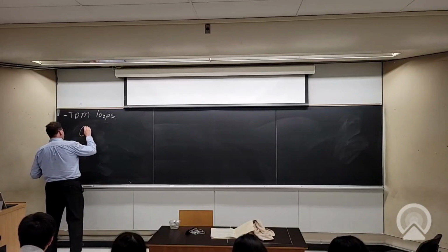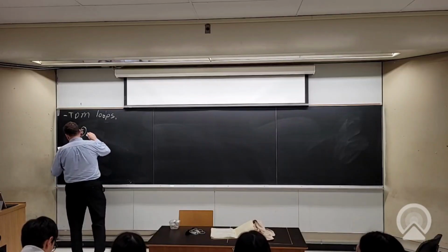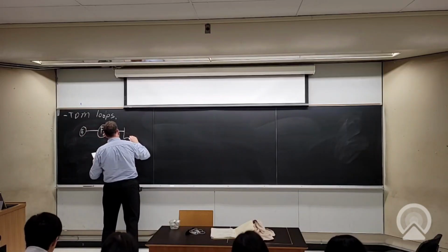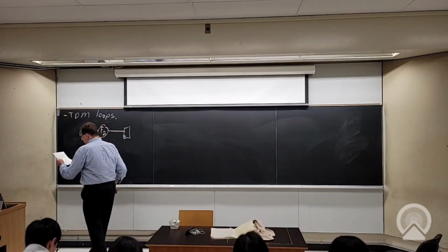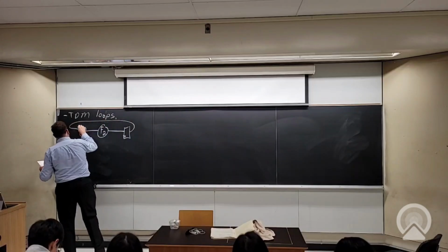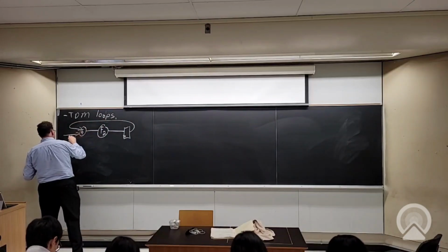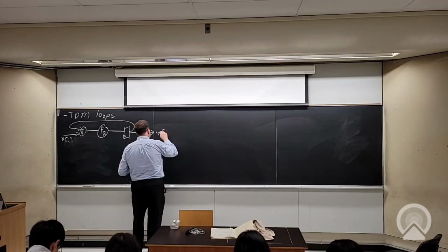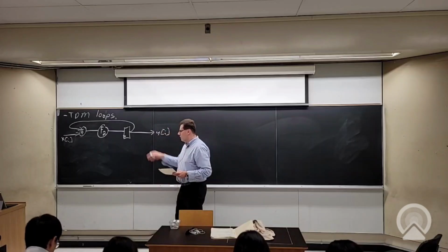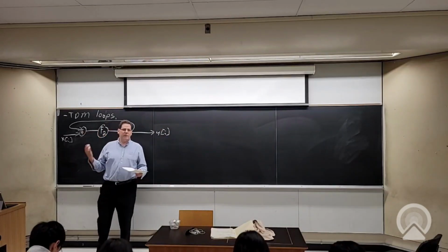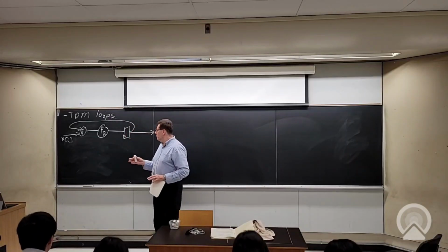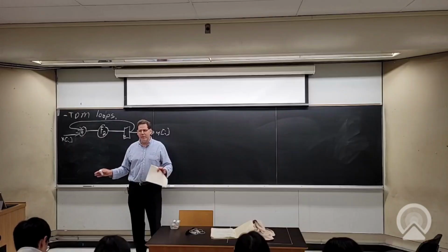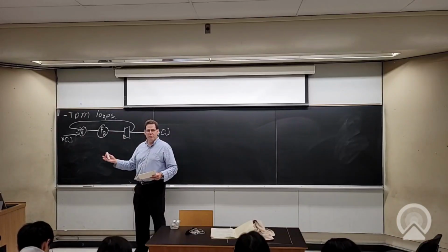So let's look at an example. Say I've got F1 and it goes to F2. This is the same example I showed you before. We register that, and we come back around, so there is feedback. We had a sequence of data going in, X of I, and a sequence of data coming out, Y of I. We concluded last week that if we stuck pipeline registers anywhere in this loop, it would change the functionality. As a designer, you might be able to rewrite this loop, but you need to actually think about it. Maybe you could rewrite it in a totally different way. That's an optimization that humans do, but no CAD tool really knows how to do.